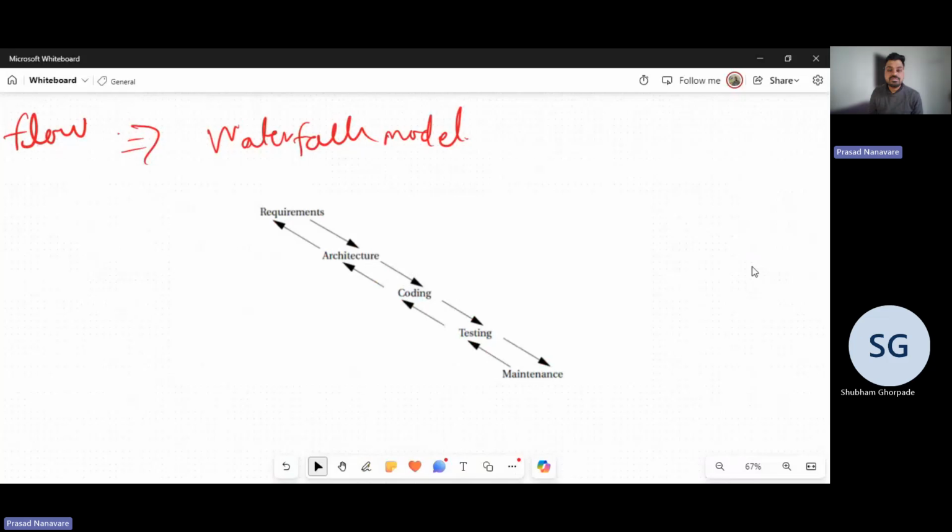A design flow is a sequence of steps that are followed during the design. The word itself is self-explanatory: design flow means the steps we follow during the design. Some of the steps can be performed by ready-made tools, and some we have to perform manually. Although top-down design is ideal, since it implies good knowledge of the implementation during early design phases, most designs are clearly not quite so top-down.